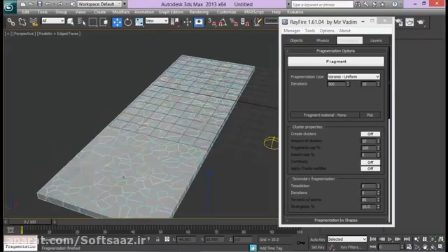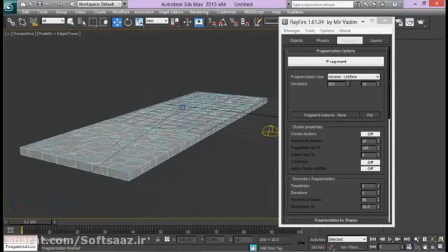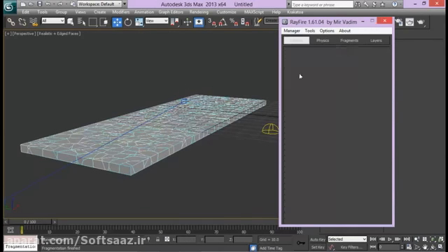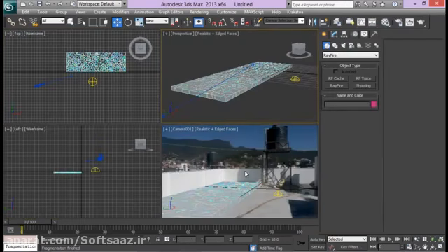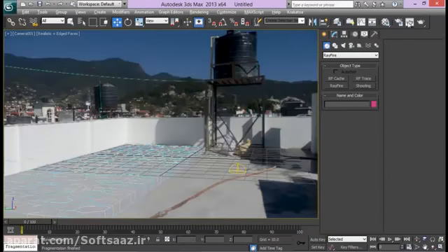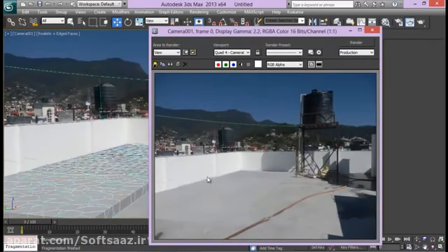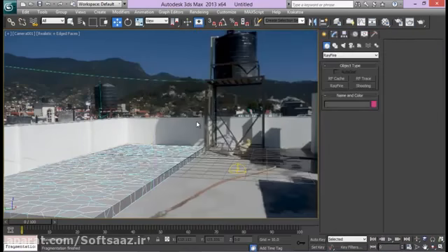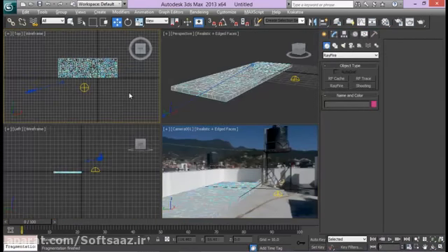Okay, now we have got quite a good size of 500 pieces of fragments. The next thing, let me clear this for a while. I'll add some of the objects later on, and let's go to camera view and see what we have rendered before. Since we have these edges looking like they are not in the scene, not matching up with our floor texture, what we are going to do is select all the edge fragments and exclude them from being shattered or from being collapsed. Also, why, I'll explain in a little bit later.